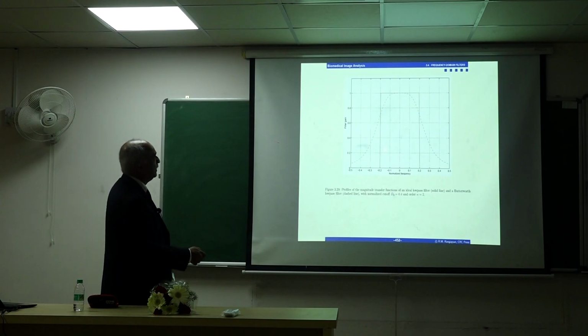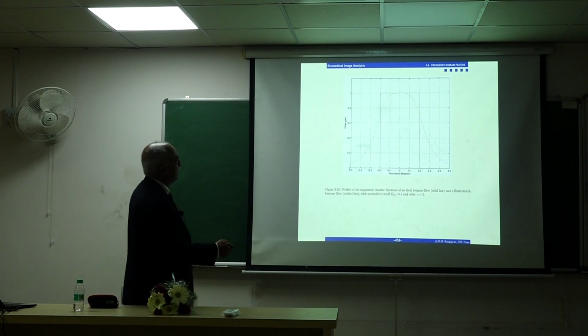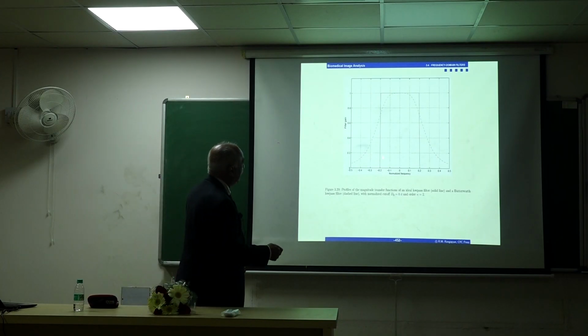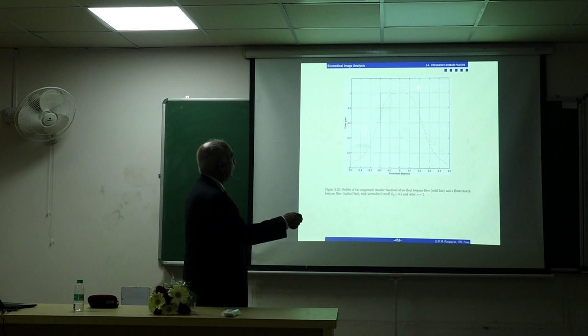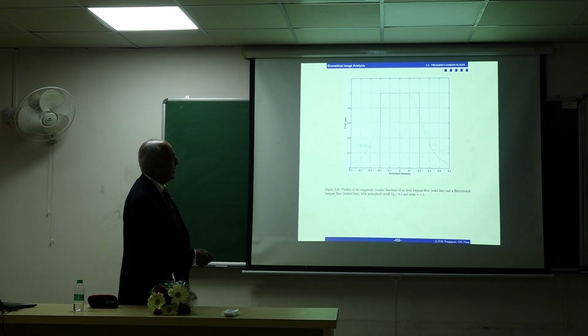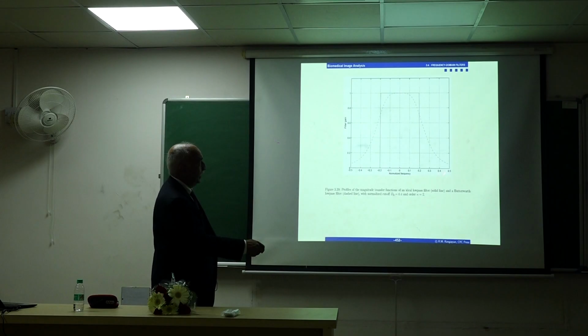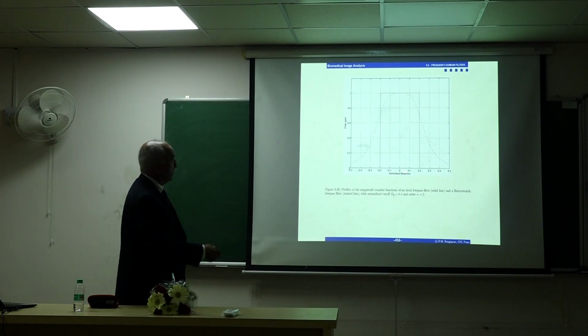If you take a section, the ideal filter is that. Sorry, it's a little difficult to see that in this plot, but there is a line there. That's the ideal filter up to 0.2, and after that, the gain is 0. The Butterworth filter has a smooth transition, a monotonically decreasing function. And this is 0.5 normalized frequency, half the sampling rate. 0 and minus 0.5.